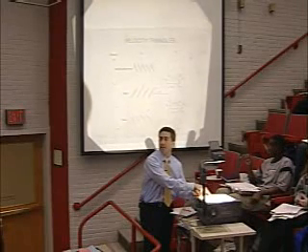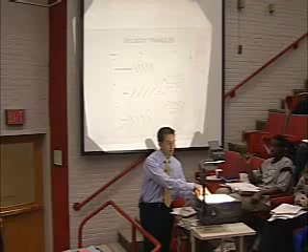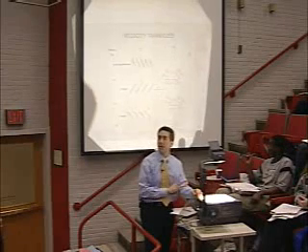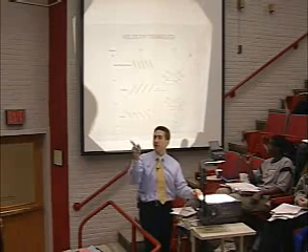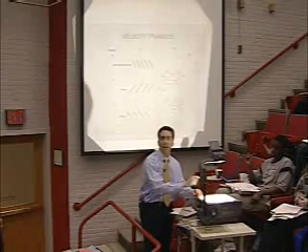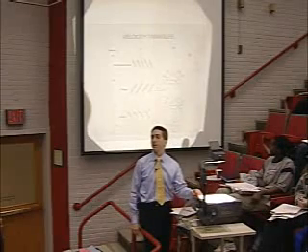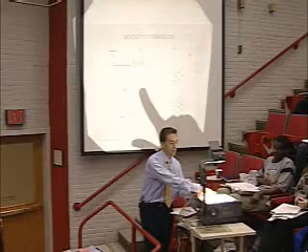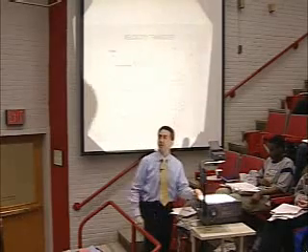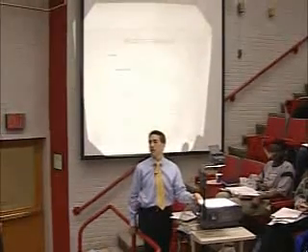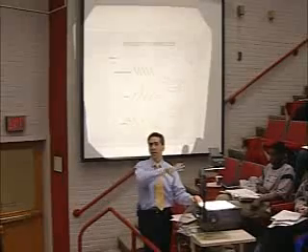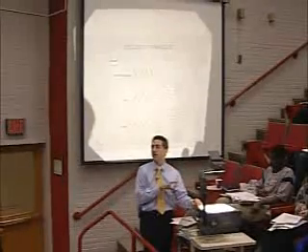When you come off the guide vane, isn't the flow going down to the right? Yes, it is. You're going to see that it happens to line up exactly with these blades when you're in the reference frame of those blades. So for this little person sitting on the blades, this looks just fine. That's how you're going to follow these rules.